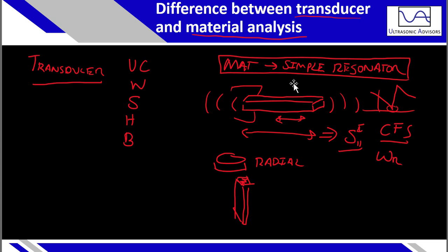If you use a long bar, it will have resonance in this length direction, which corresponds to the compliance or the stiffness in the thickness direction. Well, it's actually, the semantics are that it's a constant electric displacement, but we'll leave that aside. It basically relates to a condition which describes a material property in closed form.